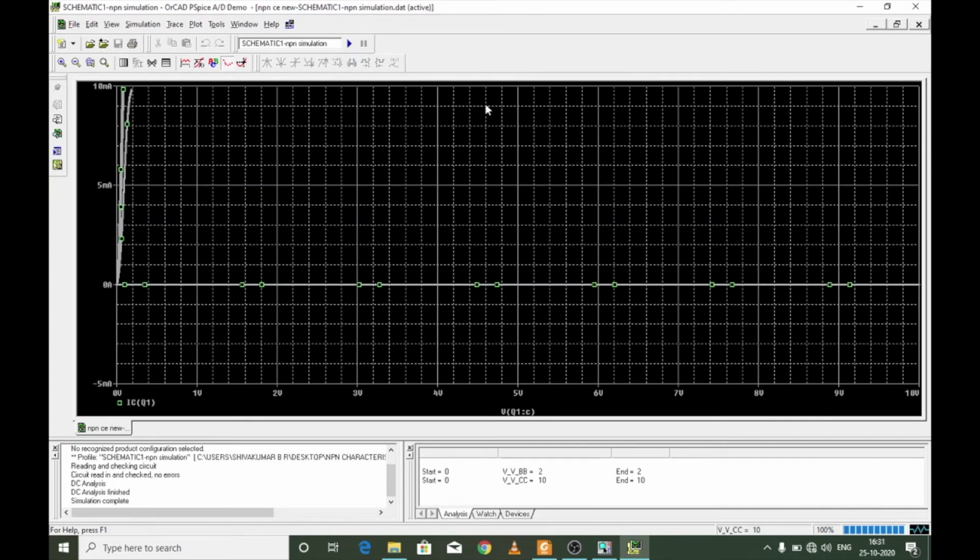This is because the voltages applied across the supplies are such that the collector to base junction has forward bias, so has the base to emitter junction, and therefore the transistor is currently operating in the saturation. In order to send the transistor into active region, we need to increase the collector to base voltage.